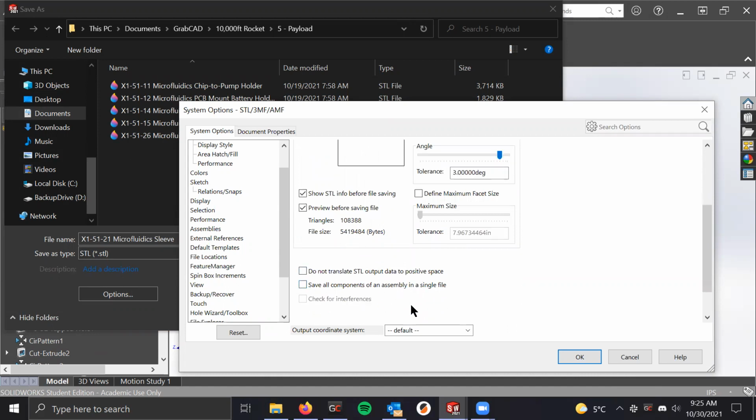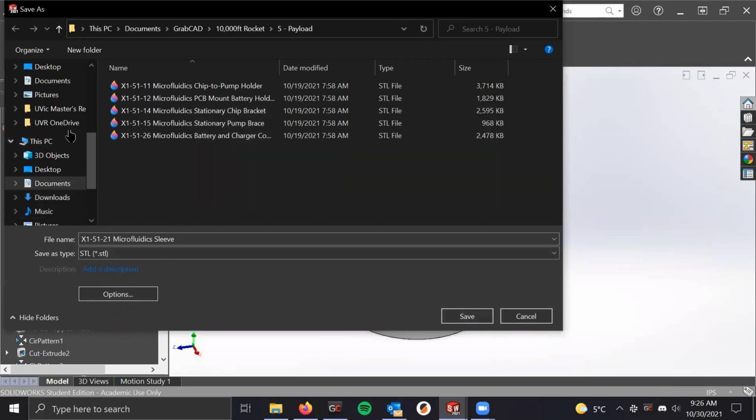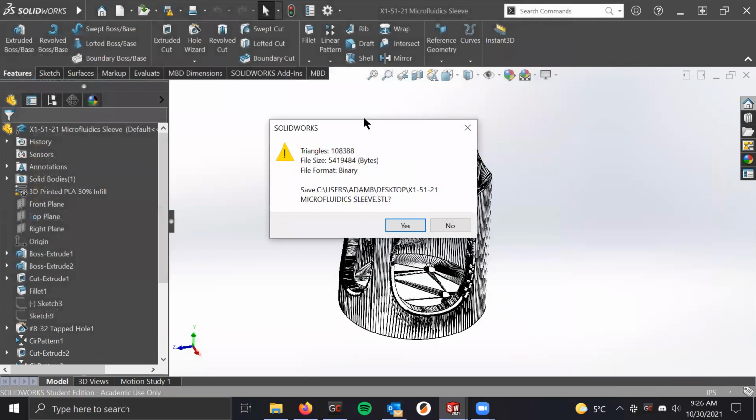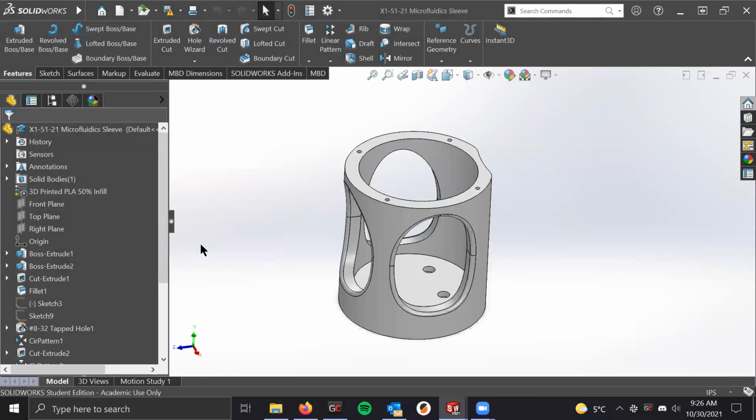If you're doing assemblies, don't do assemblies, just do parts for now. If you have big questions on this, I can help you later, but just focus on that for now. So I'm going to put this on my desktop because I don't want to screw anything up. I just want to show you. So this is our STL, and this is what gets output. As you can see, an STL is just a collection of lines and triangles. And you can see here there's this many triangles, which is cool. But yeah, you hit save and great. So that's how you save a file for 3D printing by making an STL.